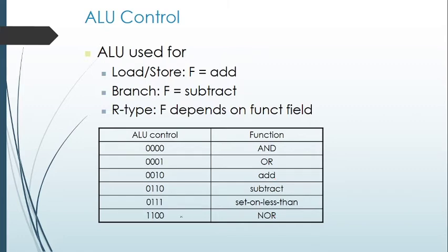The NOR operation was a little different, because a simple NOR operation is an AND operation with inverted inputs. So just invert all the inputs, and it becomes a NOR. So these are the 4 control signals for the ALU, and we know how these instructions are going to be performed by the ALU control.